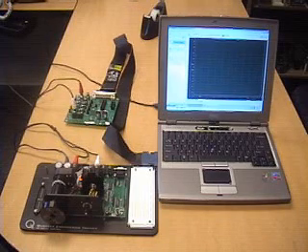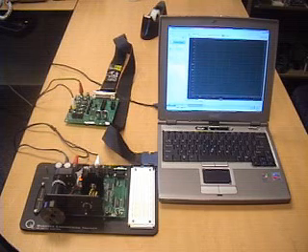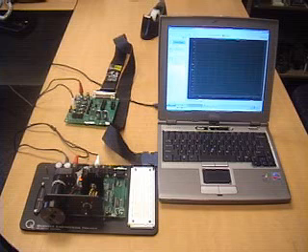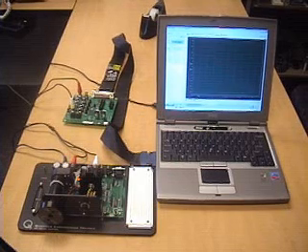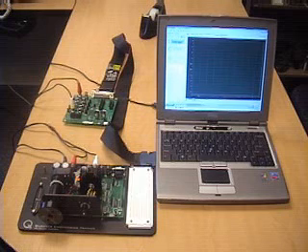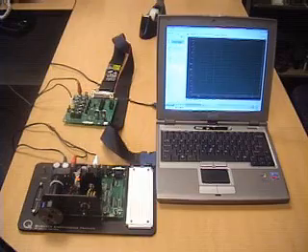In this case, we're going to do that experimentally. And so the setup here is I have my software ready to run, and essentially the software is going to send an analog output voltage to the DC motor, which will be a square wave, so essentially a step response. And then we'll read back the tachometer signal to get the response of the DC motor from that. And then from the stimulus and response data that we have received through our software, we can actually get a transfer function for the DC motor.